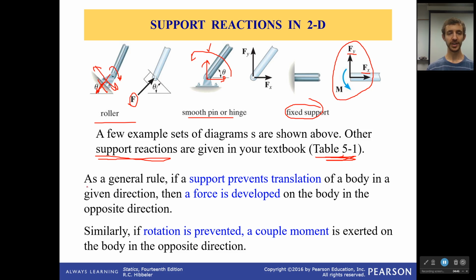And then this is more or less what I've been saying earlier. If it prevents translation, you have a reaction force that will be parallel to that translation that's resisted. If rotation is prevented, then a couple moment will be exerted to prevent that.